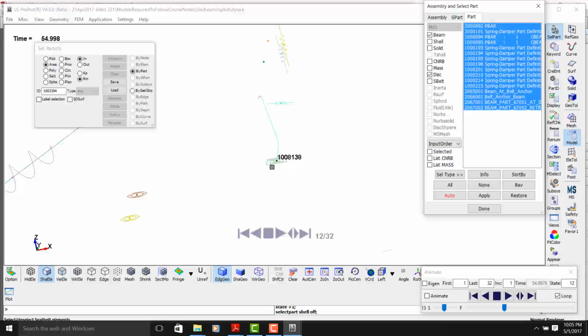But the dummy chest compression is a linear value. Length, how much has it compressed? 30 millimeters, 40 millimeters. That kind of measurement is there. But all that your chest potentiometer is giving is a rotational value. So there is something called a linearizing factor, which converts this rotation into a linear value at this point. This is also going on in a circle, kind of, but more or less we take it to be straight, and that is the chest deflection.